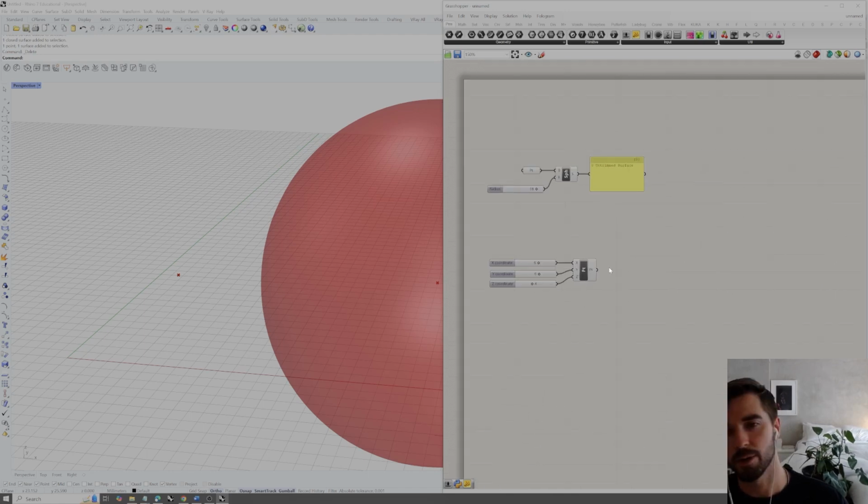As we went through in Rhino, if we want to define a line, one way of doing this is defining 2 points. So if I double click and then type line, we can see that the first option here is a line parameter, and this is to reference a line geometry already drawn inside of Rhino. Additionally, we can create a line inside of Grasshopper between 2 points, as it mentions here when we hover over this option. So I'm going to select this,